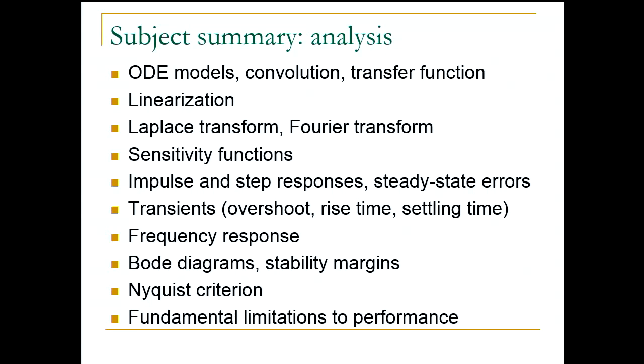We then also learned how to obtain impulse and step responses of linear systems, and we also talked about transients, so overshoot, rise time, settling time, and also steady state errors. We also learned how to relate these features of the step response to properties of the transfer function. We learned how to obtain them from the transfer function and locations of poles, for instance, of the transfer function to overshoot, rise time, settling time.